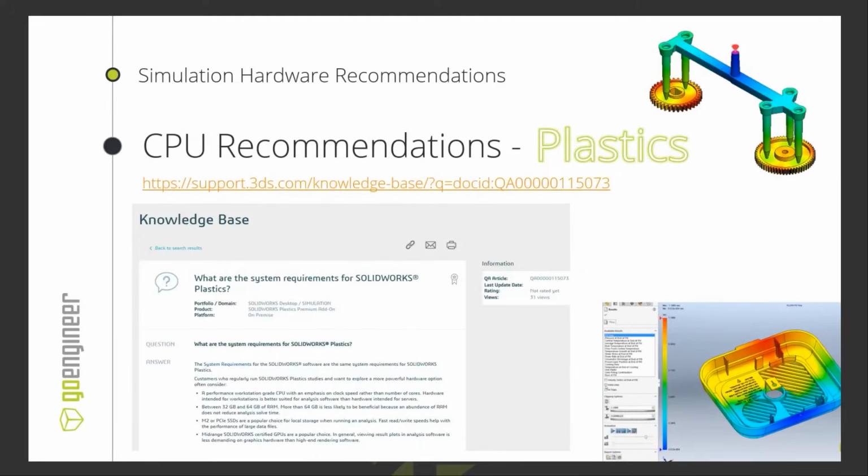Plastics, another one near and dear to my heart. Plastics solvers, similar to Flow Simulation, are very multi-thread capable. We're just starting to do some benchmarking on multi-core performance of plastics. So I don't have an upper limit that I can tell you, but I know, in just some testing personally without going through a full-blown benchmark profile, plastics is multi-thread capable somewhere in the 16 to 24 core CPU range. How much bang for the buck you get beyond that, I really don't know.